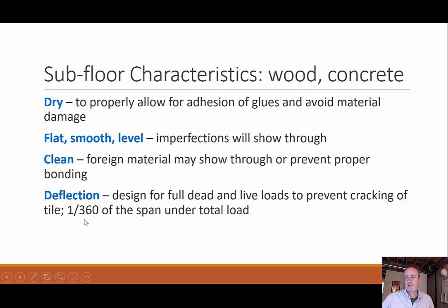Deflection is a consideration. So what do we mean by deflection? If our floor can't support the load, the dead load and live load, we talked more about dead loads and live loads before, if it can't support it enough and we have deflection, almost like a bouncing, then we can get cracking of our tile. Our wood will pull loose and we'll start to get creaks.